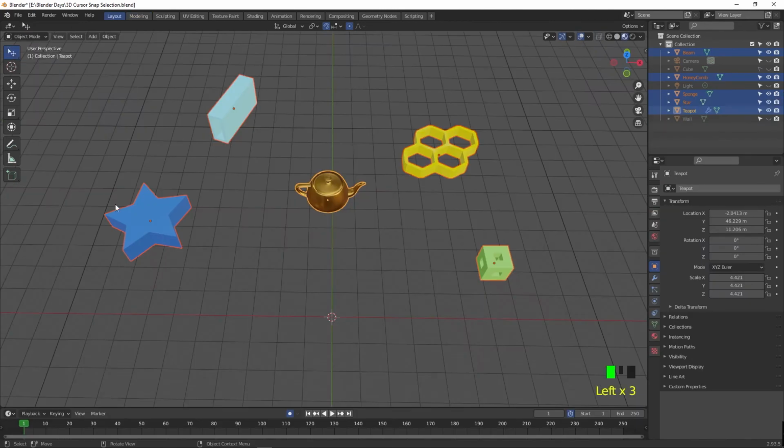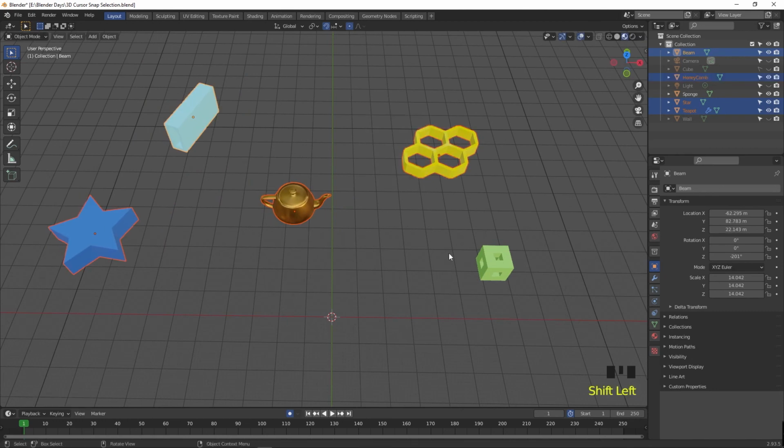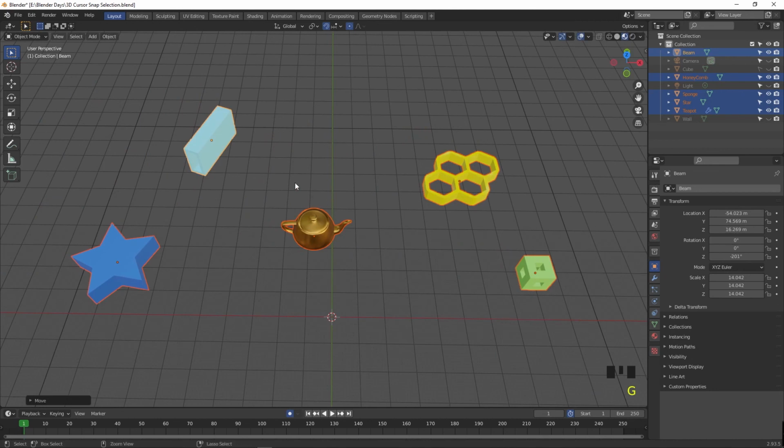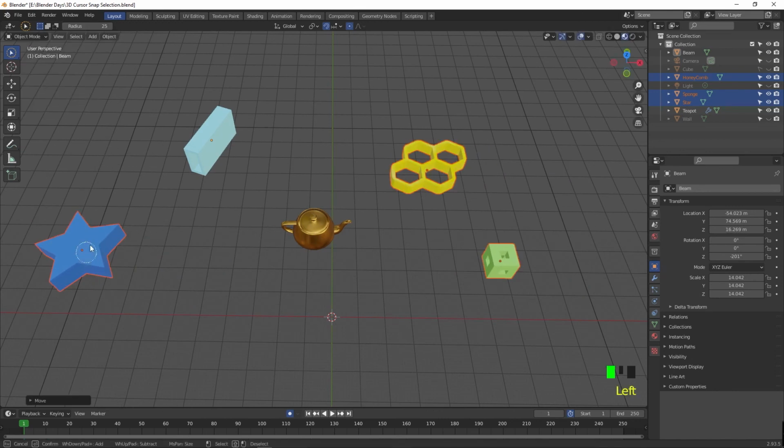Let's recap. Tweak tool to select and activate. Select box for rectangle box selection. Hold Shift and drag to add to selection. Hold Ctrl to remove the items from the selection. Select circle. Click and drag on objects to make selection. With lasso, make free selection to select the needed object.